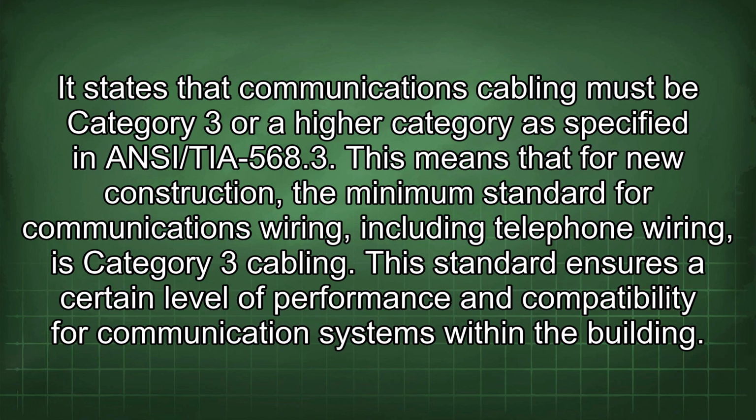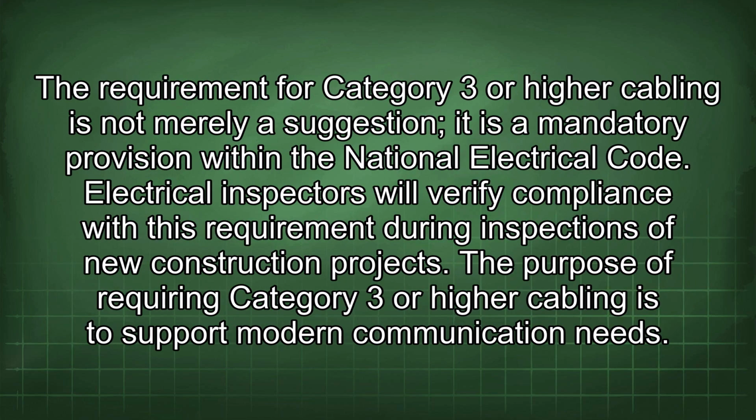This standard ensures a certain level of performance and compatibility for communication systems within the building. The requirement for Category 3 or higher cabling is not merely a suggestion, it is a mandatory provision within the National Electrical Code. Electrical inspectors will verify compliance with this requirement during inspections of new construction projects.